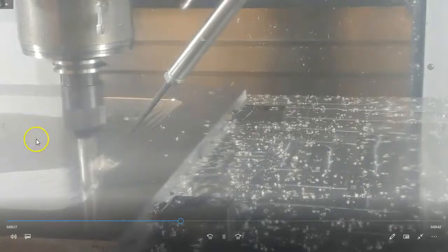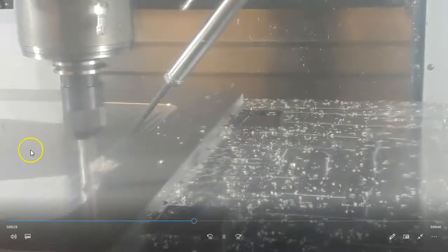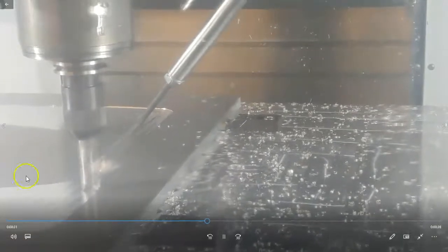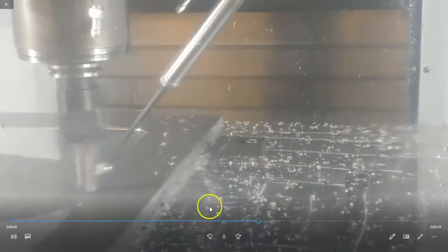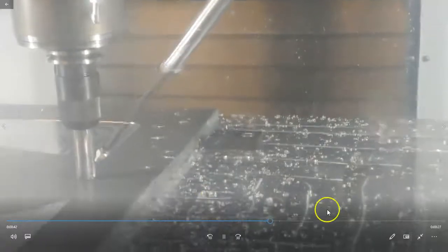And this material started at the middle, or this tool started at the middle of the material and has already made the concentric pattern, but these are higher spots and this is a lower spot where it's leaving the raw material. So as I go through this process, I'm trying to hold as close a thickness to the print as I can, at the same time that I'm getting this as flat as I can.